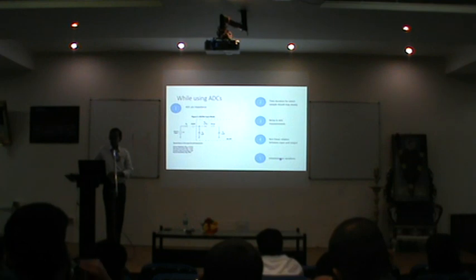And the last one is your instantaneous variations. Take speed: the mechanical inertia constant in a motor is pretty high, which means the motor will be running at pretty much constant speed. But when you look at the digital readings, even a variation of 1 or 2 will be there. One moment it will show 1231 RPM, next it will show 1229 RPM. There will be a slight variation there.